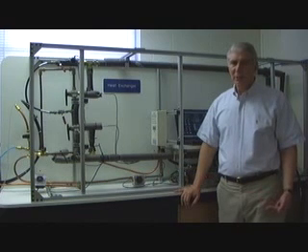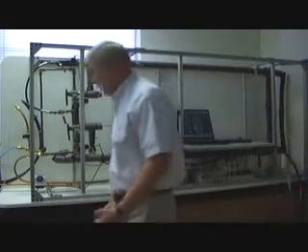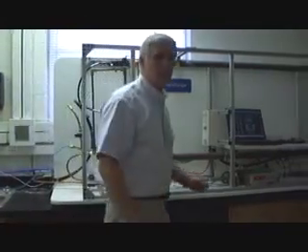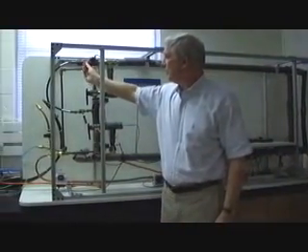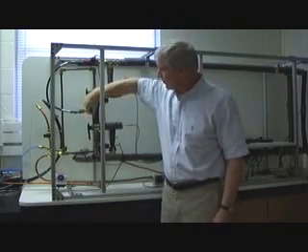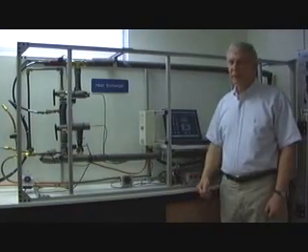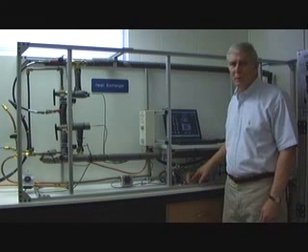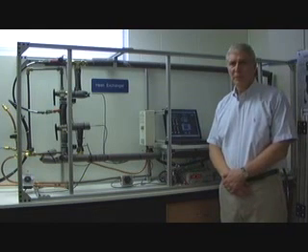When you're done, upon completion of the experiment, I would like you to turn off the main water valve over here on the left. Turn off the hot water heater with the handle on the wall over here. And open the red-handled valves so they're in the open position to relieve pressure on the system. If you're the last group of the day, I would like you to also turn off the computer and turn off the power supply. And that completes the double pipe heat exchanger demonstration. Thank you.